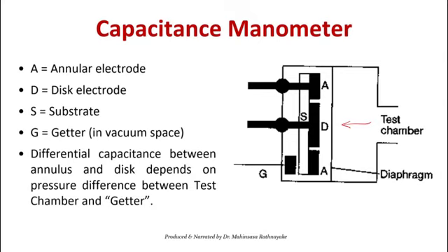The Wheatstone bridge, right? So that type of circuit will be there. So the displacement can be converted as a resistance of a certain resistor, and then the voltage can be changed with the resistance. Then the output voltage from the bridge circuit is a function of the resistance change due to the strain in the diaphragm. Strain happens with the displacement, right?